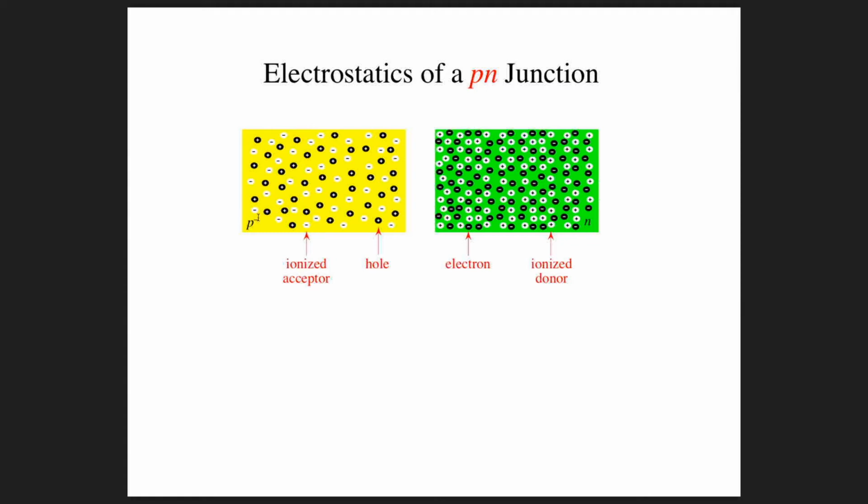And if I don't have a subscript, or a superscript here rather, and it's just P, or like over here this n-type region just has an n with no superscript, that's a moderately doped region. And that moderate doping level might go from like 10 to the 15th up to maybe like 10 to the 17th or 10 to the 18th per cubic centimeter.